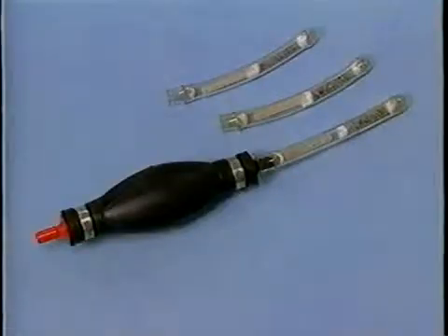Negative pressure means that when the room door is closed, air is flowing into the room from under the door. No air from the room can escape out to the hallway. Whether or not a room is operating under negative pressure can be verified by a number of cheap and easy techniques. What you need to confirm is that there is an air current flowing into the room from under the door. The most common method is smoke testing.